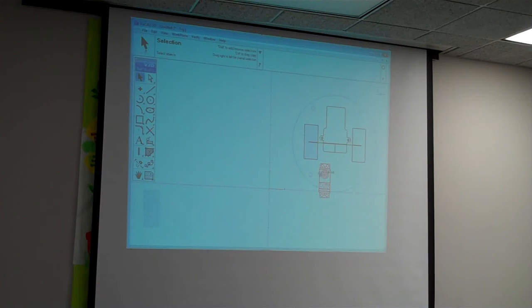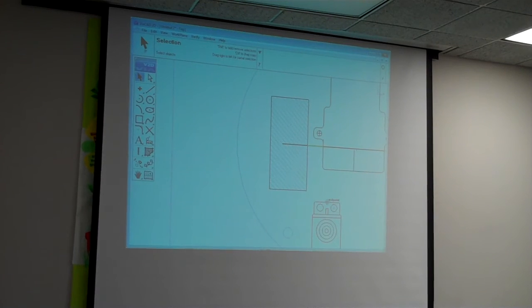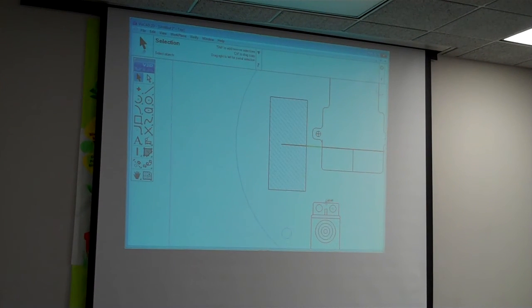But once again, here's where these drafting features come in. Let's zoom in a little bit. Whenever I get close to something, like the midpoint, or the center of that circle, see how it says center? Center? Midpoint? So I know I'm on the exact center of that little chunk of drawing. So I can take that, come up here and just touch that center there, and then as I come down, see, it's giving me, so I know I'm on that center line. So we'll put it right about there.